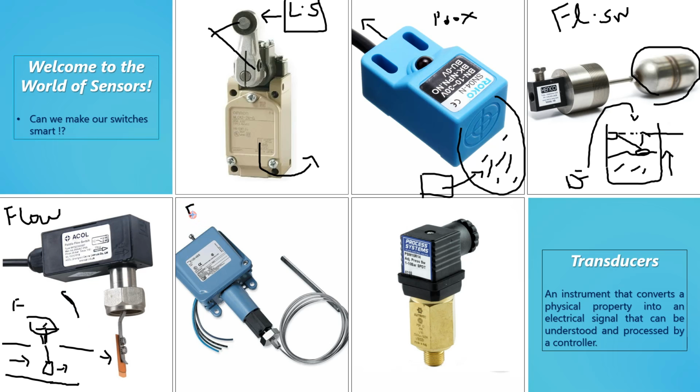Here we have temperature switches or temperature sensors, right? Now this here is a temperature controller, and this is a thermocouple, a sensing element. However, there are some other, easier methods, one of which you will find in your home whenever you press clothes. It is a bimetallic strip. Now, in material sciences, you will know that different metals have different rates of expansion. One of them has a higher rate of expansion, and one of them has a lower rate of expansion, and they are physically fused together at a surface, so they cannot be separated from one another. So they are constrained to expand together. However, due to their different rates of expansion, they will bend a little bit, and hence they can either make a contact or break a contact upon expanding. And this is the common principle used in home iron presses.